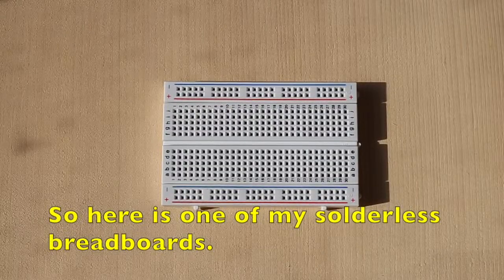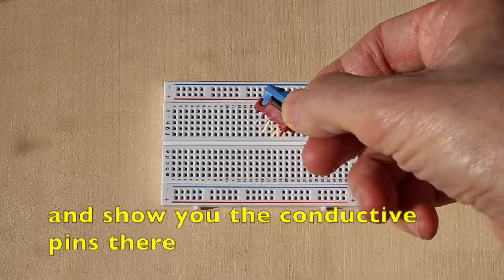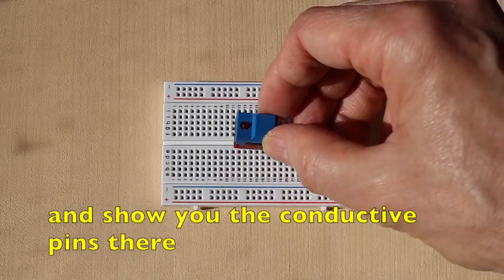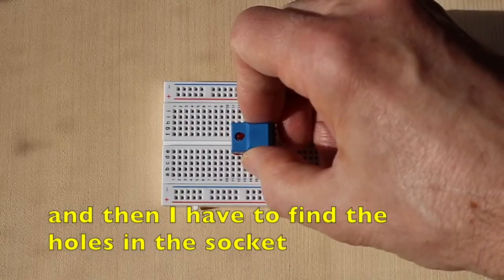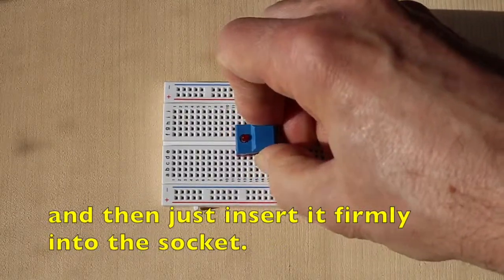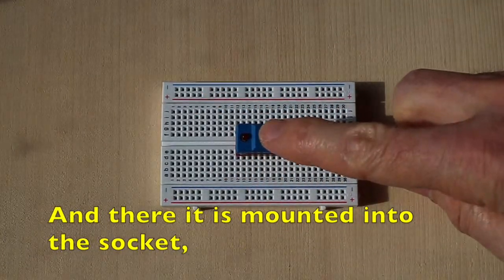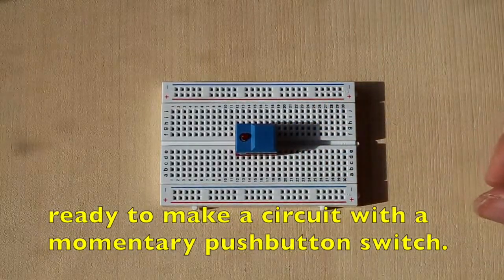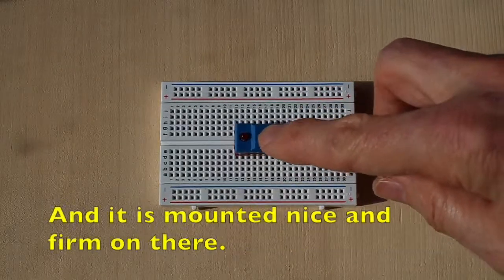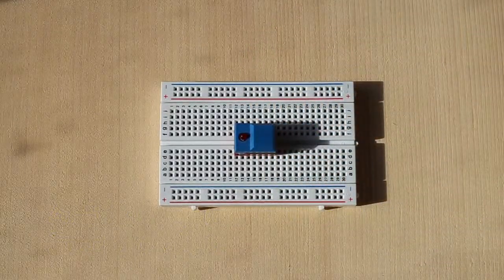So here is one of my solderless breadboards, and then I'm going to take the switch and show you the conductive pins there. Then I have to find the holes in the socket and just insert it firmly into the socket. And there it's mounted in the socket, ready to make a circuit with a momentary push button switch. And it's mounted nice and firm on there.